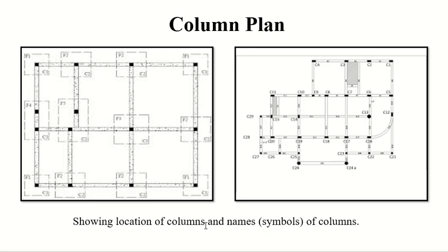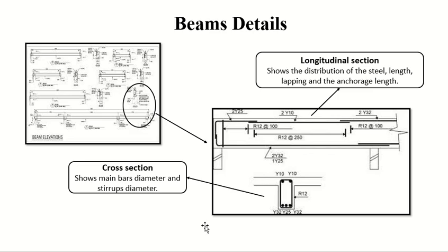Size you can see from here as well. I don't need to put a code here for the size. What else? I told you for the beams. Much easier to recognize. Recognize what? Different. What I am trying, description. We will prepare a column schedule as well, like I showed you the beam schedule.